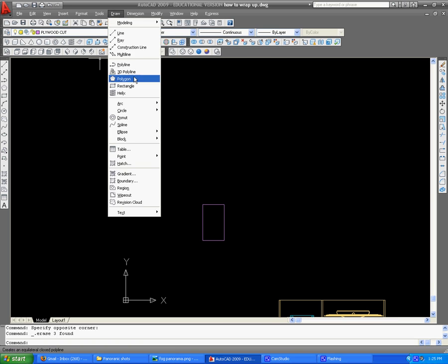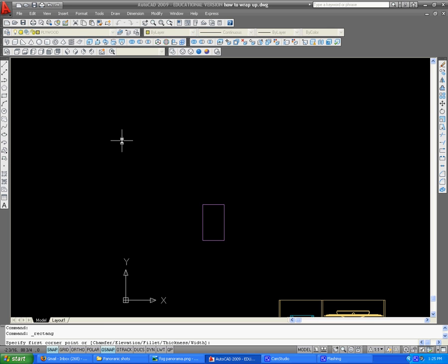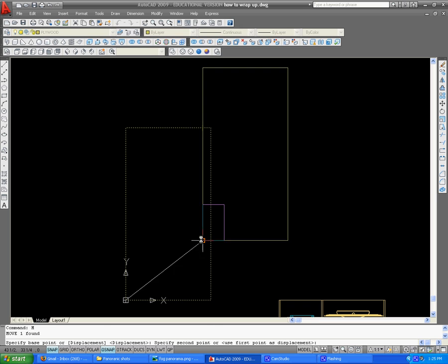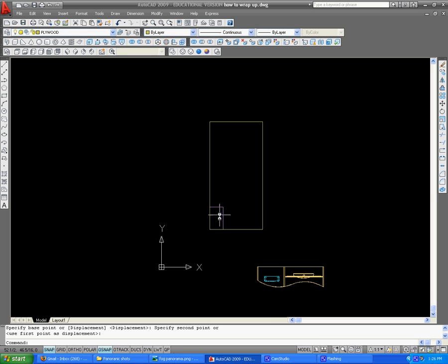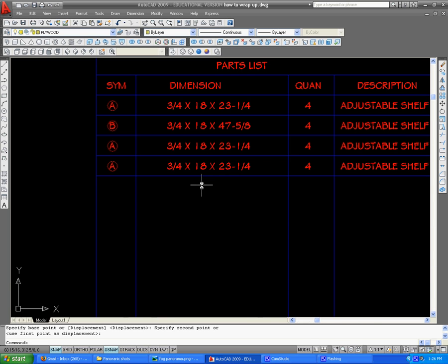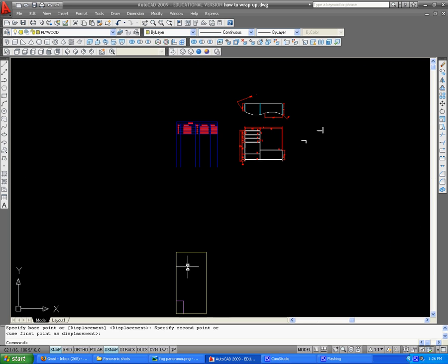So let's try this just one more time. We go on the plywood. We go 0, 0, but these were whole numbers. I don't know why it did what it did. We go over 48, which is the X distance, and then 96, which is the Y. That's more like it. I'll put that down. And there is one piece of wood that can be cut out of this. These are all 18 inches, so you can just put them right in a line with each other. So you want to use your plywood as efficiently as possible.